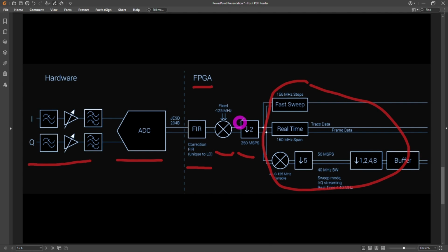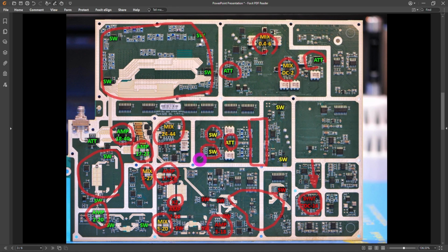In the instrument, where you do have the IF option, you actually do lose the upper end of the mixer range. So if you don't get the IF option, you get the sweep all the way to 43.5 gigahertz. But if you do get the IF option, you get a 1.5 gigahertz IF output, but then you lose the upper few gigahertz range, and that's because you lose the IF digitization of this final mixer. That's a bit unfortunate. That's probably my only real criticism of this architecture, and that's because they just couldn't fit another switch here to be able to allow that to be switched as well.